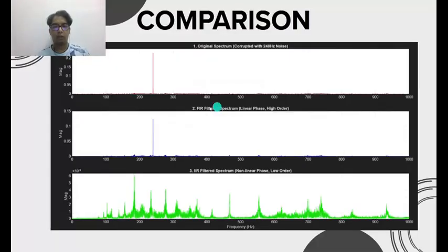So as you can listen, the frequency of 240 Hz, which is the spike over here, destroys the original song. So we apply FIR and IIR to eliminate the spike at 240 Hz. After FIR, our spike becomes lower, which is half of the original spike, from around 0.23 or 0.24, and then it becomes 0.14 or 0.13.